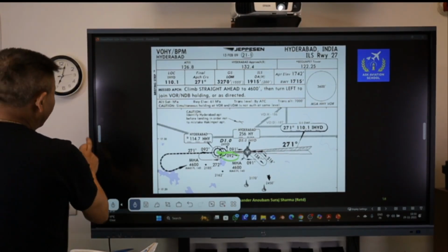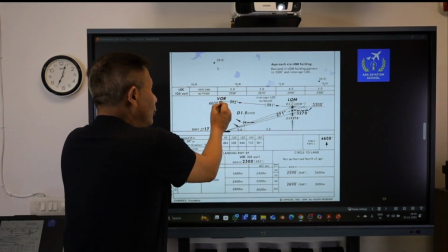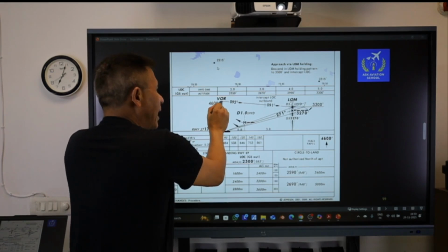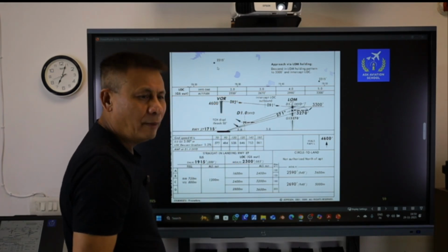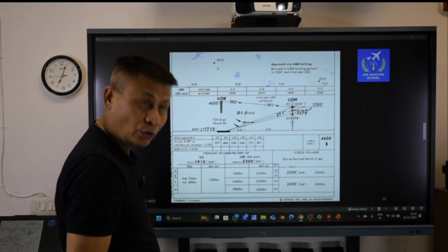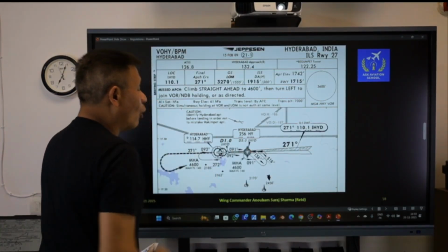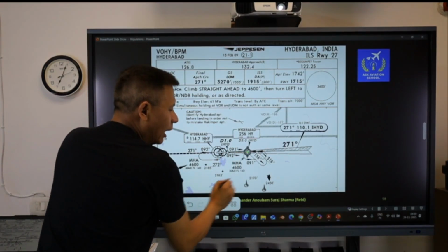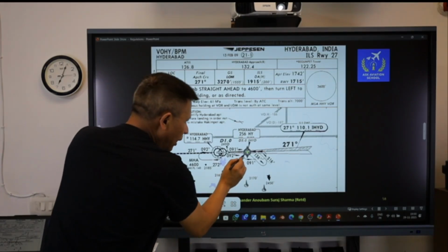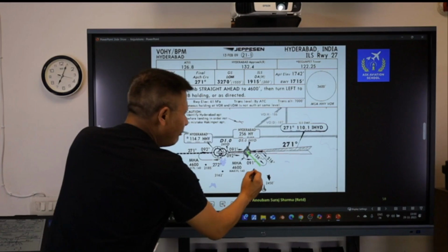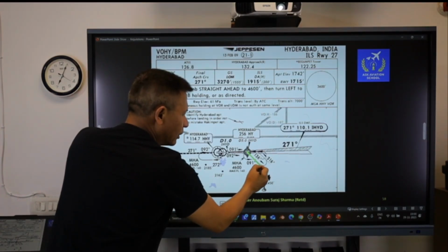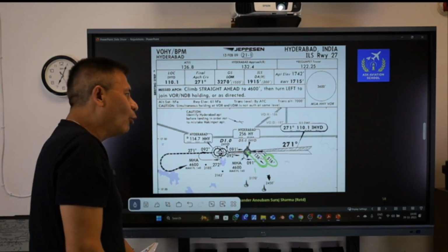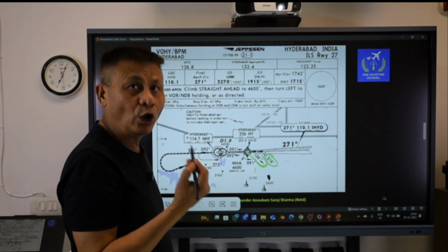I will show you the vertical profile here. In the vertical profile, you are over the VOR at a height of 4,600 feet, and thereafter I will be proceeding out on a magnetic track of 092 till I reach over the locator outer marker. At the locator outer marker, I will be carrying out a right procedure turn on a direction of 136, fly for 1 minute, and thereafter carry out a right reciprocal turn on a direction of 316, and wait till I intercept the localizer signal.